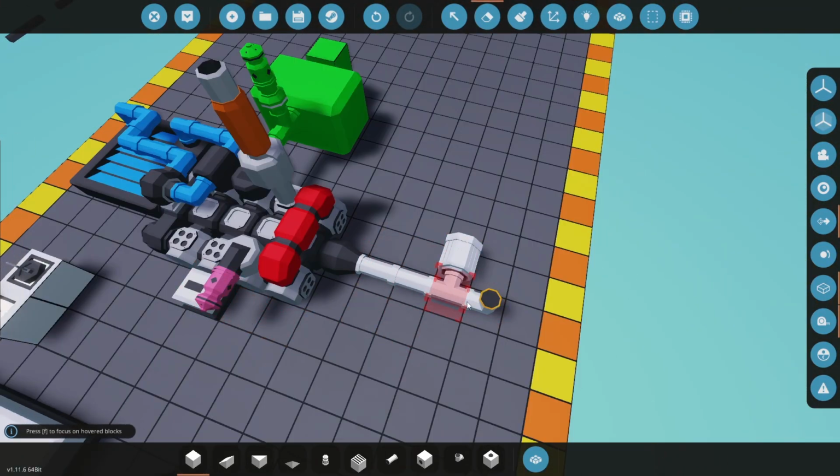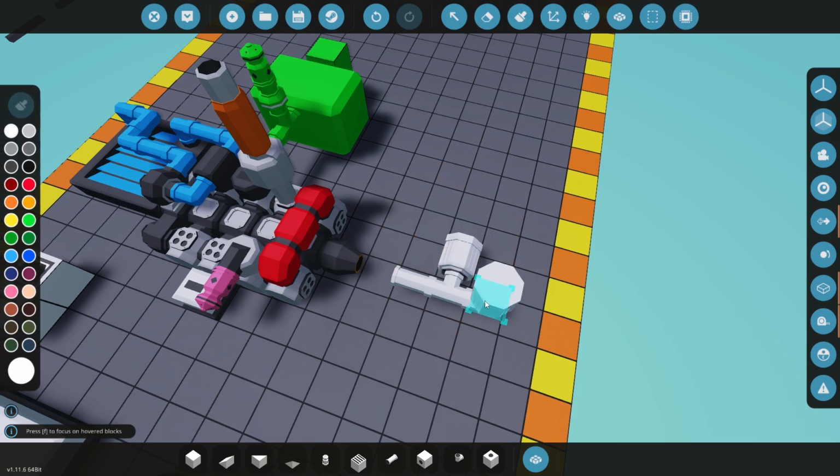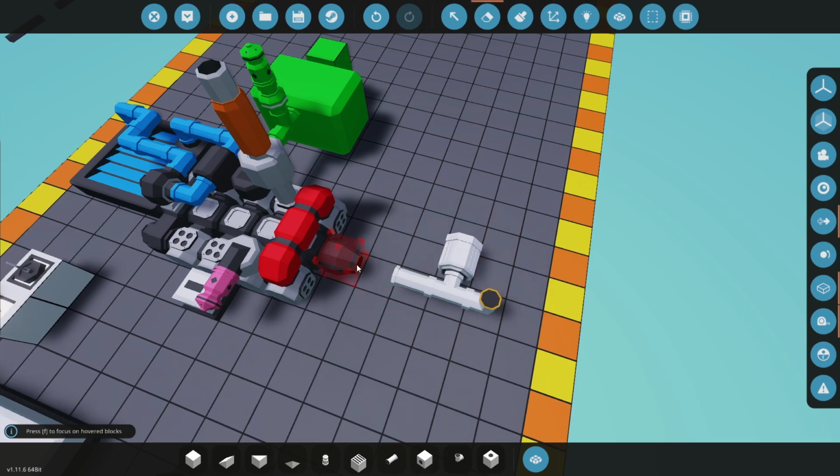We covered some of this stuff. Again, if you throw on one of your engines and it's not working, say it stalls out, say it has any issue, my first plan of action would be to cut whatever is here and just see if the thing turns on. Because now you're not putting any load into the system, whatever it is you have here, whether it be wheels or generators. You just want to see if your engine runs.